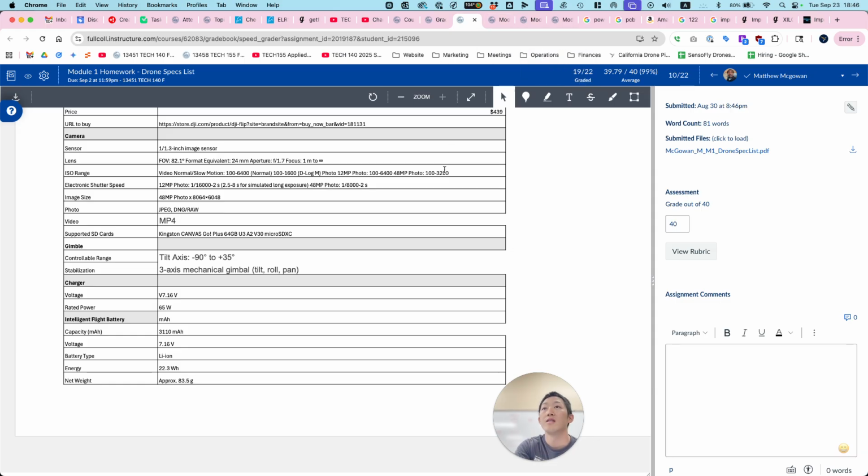Question on that. A lot of times they'll list the polarity for those barrel plugs. Is that applicable? I've never really seen where it matters. I mean, we do have to pay attention to that. I guess sometimes some manufacturers might switch the polarity. But typically there's not much you would need to worry about, especially if you're buying something off the shelf. It's already been designed so that they'll match up. But if you're building your own thing, or powering it from a power unit like this, you would need to know the polarity of the barrel. So I would think that's probably why.